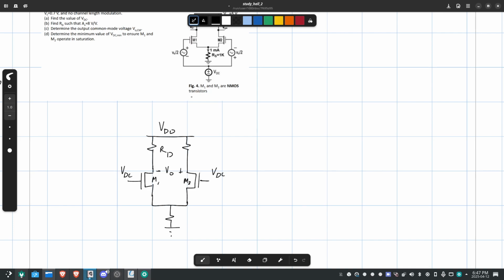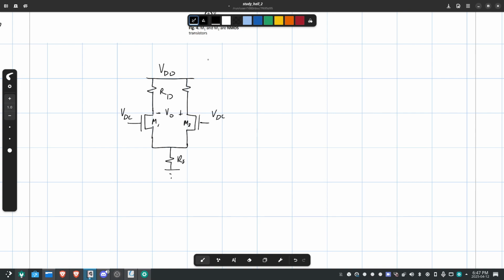And then, okay, here we go. We're going to have 1K RS here. Now, this is effectively common mode, right? Because both sides are getting the exact same current. So we could pull that same trick we did earlier. This is going to become 2RS and then 2RS. In case I didn't explain it earlier, this is the exact opposite of parallelization, where we're uncombining it, right? And if you do 2RS parallel with 2RS, you just get RS. And now, knowing that, we can cut the connection in the middle, following our common mode rules. And so now we can cut out the entire other half of the circuit.